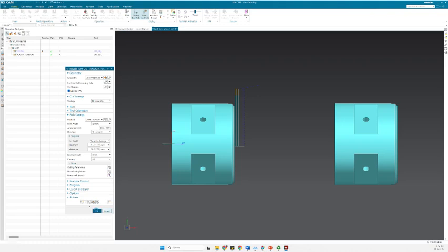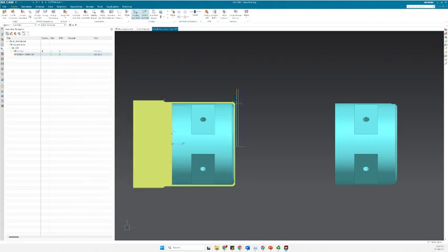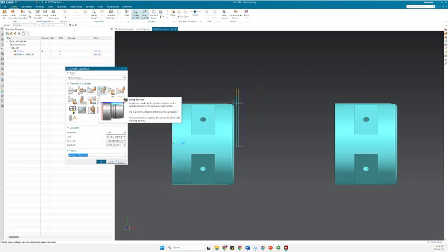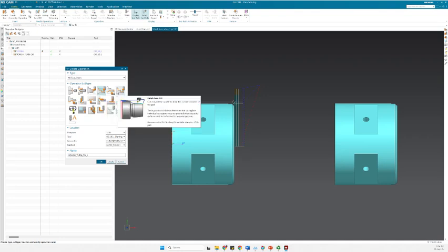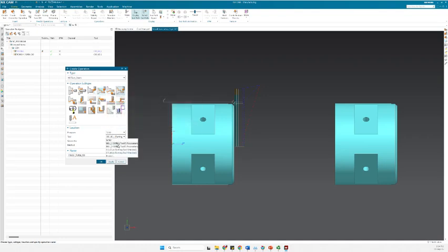So after that, I go to the next one, which is the finishing of the outside diameter together with the facing. So I can just create another operation, and this time I will select the finishing OD. So this is the finish OD. Let's say this time we're gonna use a tool with a sharper tip or smaller nose radius, so that it would be better for the surface finish.